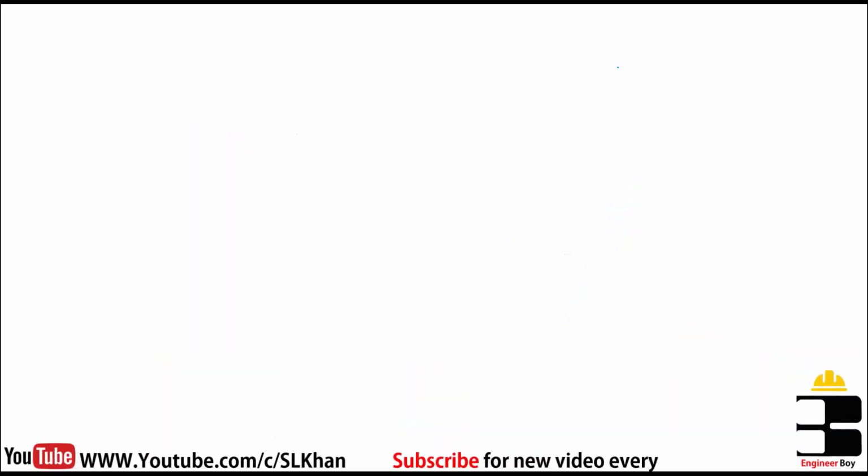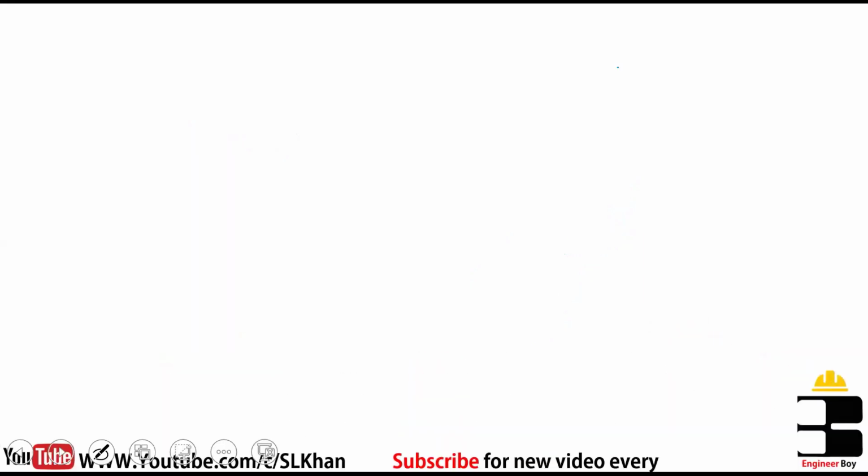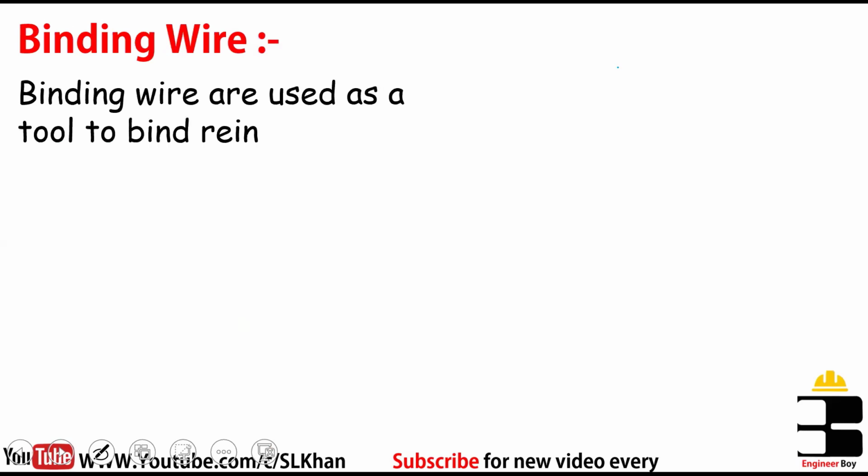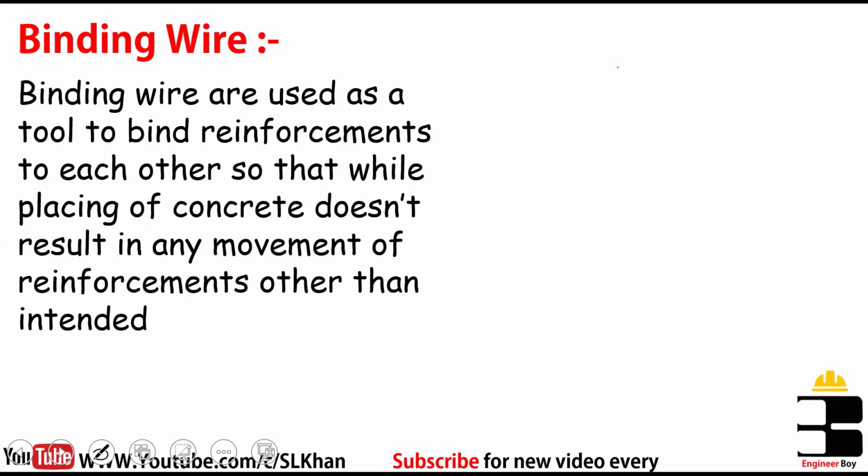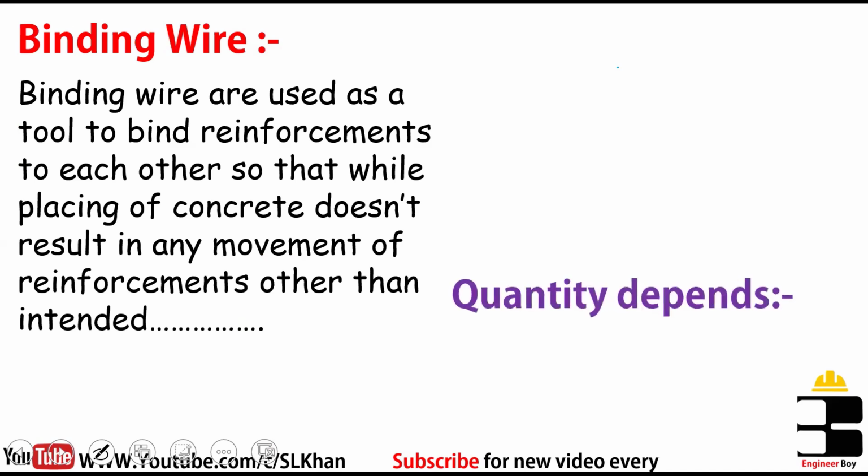However, if the project is heavy, then you have to determine the quantity of binding wire as well. And remember, binding wires are actually bars with very small diameter, okay? And they are just used to bind reinforcement together, okay? So while placing the concrete, that may not result in any movement, okay? So the reinforcement just stays in place. Now, the quantity of binding wire may depend on the structure type and the type of the bar, okay? By type of the bar, I mean the diameter of the bar, okay? If the structure is heavy, then the quantity of binding wire may increase.